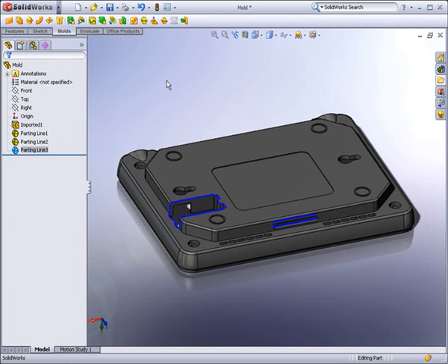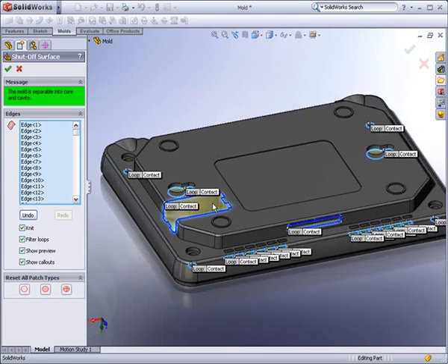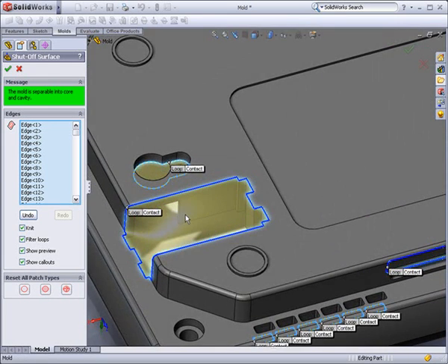Parting lines can be leveraged for multiple purposes in SolidWorks. For example, generating shutoff surfaces or identifying areas that will require a shutoff later in the design process. The Shutoff Surface tool automates the creation of surfaces, closing off all the tooling geometry.